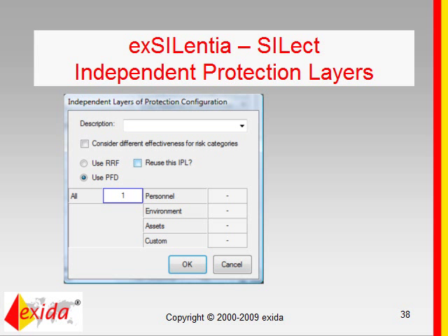It would protect the asset in that the vessel will not rupture, but you could argue that, hey, the environment is still damaged. This protection layer is not adequate for my environmental protection. So you could say, let's say a 0.1 for personnel, probability of failure, a 1 for environment, and maybe a 0.01 for assets. So you can consider different protection layer effectiveness for the different risk receptors.